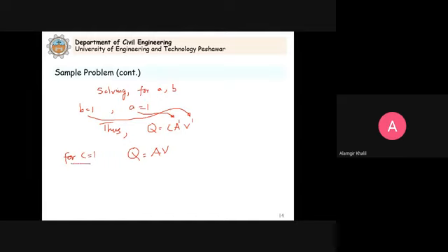Now in this case we already see that C should have a value of 1, and this is what we already know, that discharge is equal to the product of flow area and flow velocity. So you can see here how dimensional analysis helps us to develop a functional relationship between the variables.